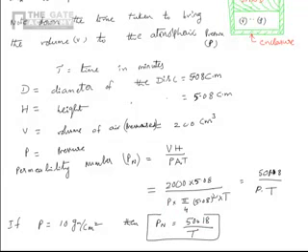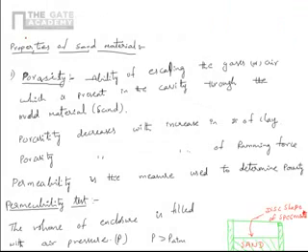So porosity is a property of molding sand. Permeability is a measure of quantity of porosity. So permeability number tells us how much is the porosity. If the time taken is more, it is less porous, inversely proportional. This is one of the important metrics, porosity. Next, strength. Strength is also one of the important properties of sand mold.